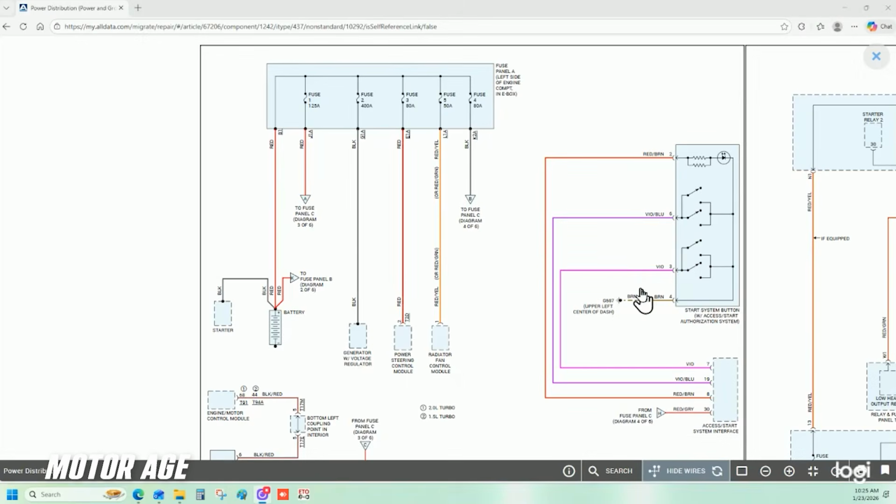So again, rather than approaching the whole vehicle, we are going to leverage service information, the PicoScope and its capture capability, along with a couple of amp probes to determine which of those 5 circuits possesses the current flow during the parasitic drain. When we come over to the vehicle with our amp probe, we are going to be capturing current flow leaving the battery. We're going to be using that current flow as an indicator that a problem is present.